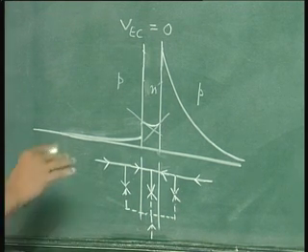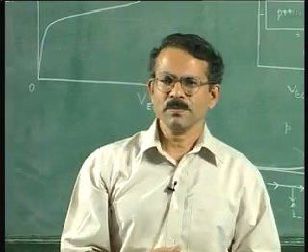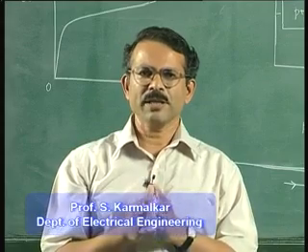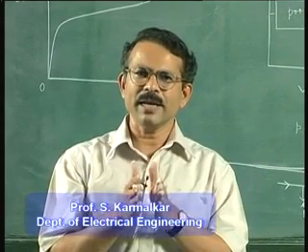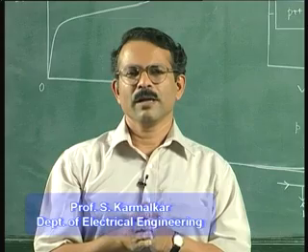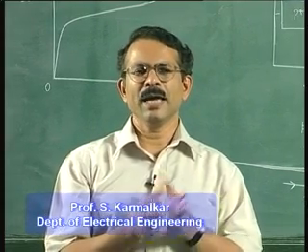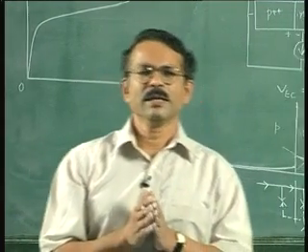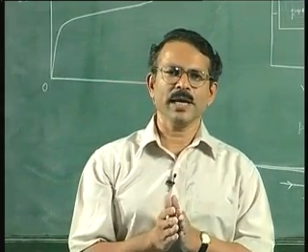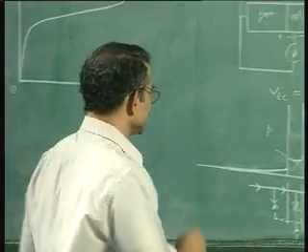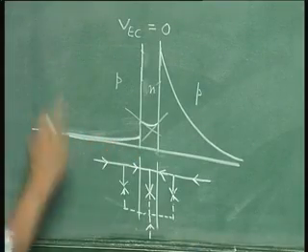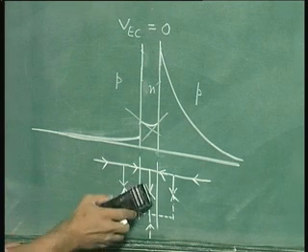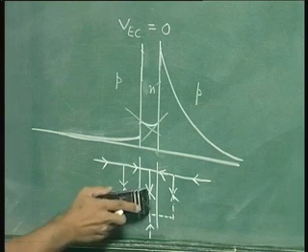Now to simplify the picture, we will use the fact that in a modern transistor the recombination in the base is negligible because the base is really very thin. Alpha is therefore decided by the injection efficiency, which is equivalent to saying that alpha is decided by the current that is injected from the base into the emitter. So alpha is decided by this current and not recombination here. Therefore this part of the picture can be removed to gain a simple understanding of the situation.